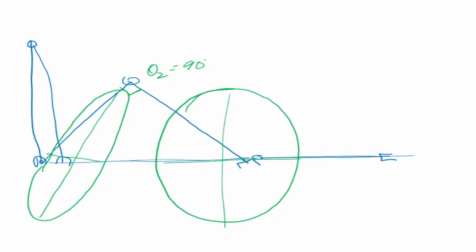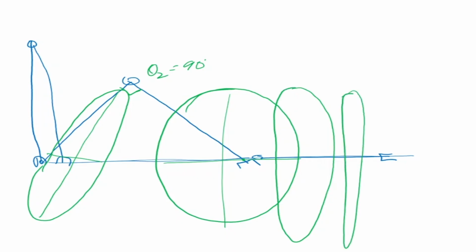Then as it starts moving this side, it will start shrinking into an ellipse. It will become like this. So it is becoming from a circle, an ellipse, more and more thin, and finally when it fully stretches out, it will become like this. So what is changing is the values of sigma 1 and sigma 2, and this is magnitude. Sigma 1, sigma 2 is magnitude, and there is also direction.